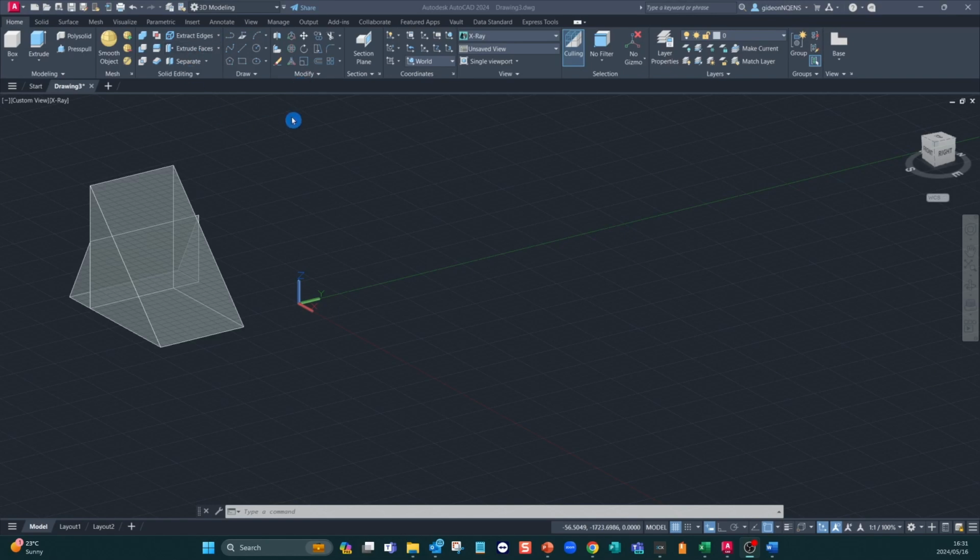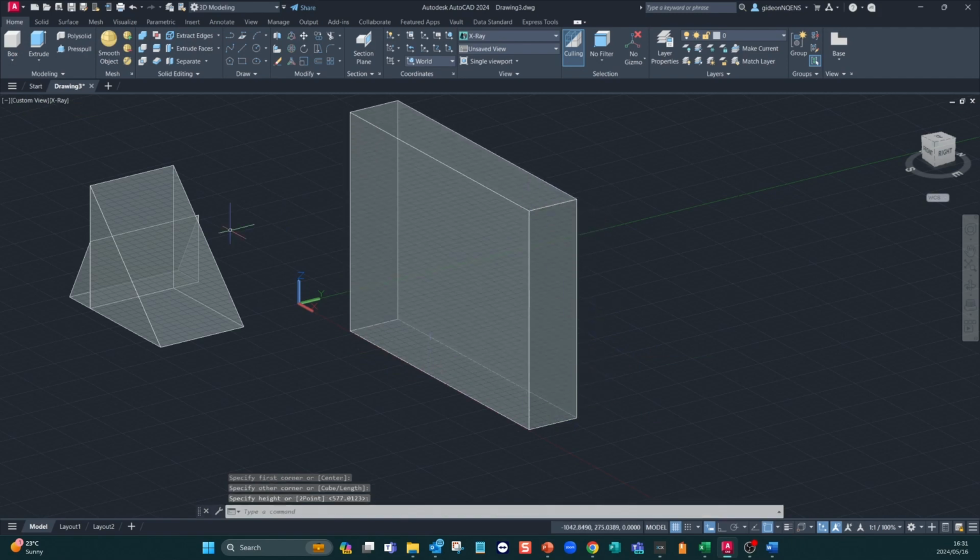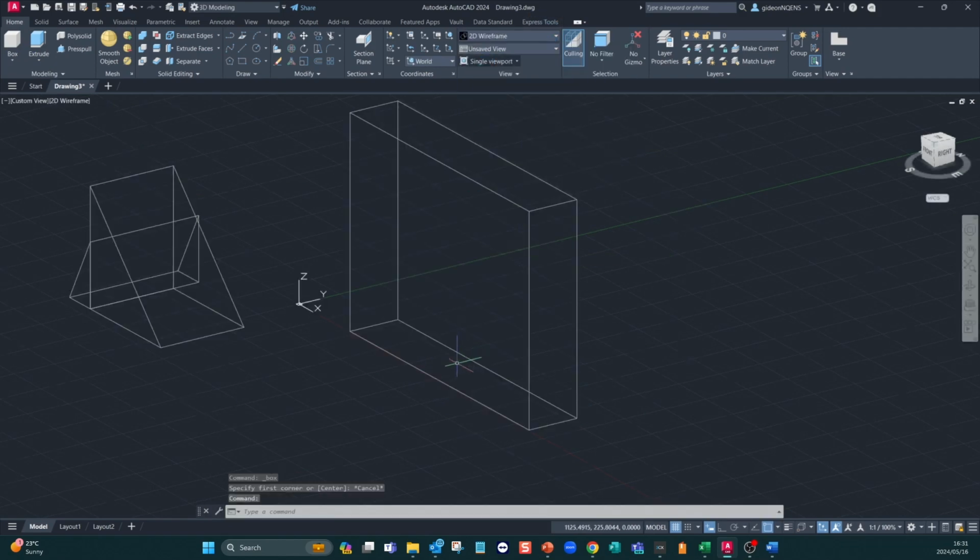Another very good example of how we can utilize the alignment tools is to align specific shapes like an archway or doorway, and align the door to the archway, or so on, gates to a wall. In this example, I'm just going to draw a quick normal square block, going to draw another square block on the inside. I'm just changing this to wireframe. Let's say from that point, I just want to track it to that specific size.